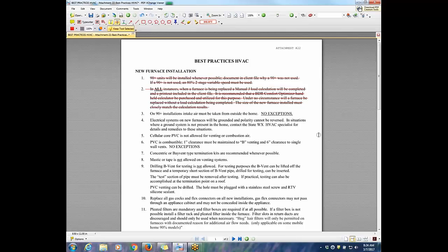And now that appliance, if you do it that way, is no longer a direct vent appliance, so it doesn't fall under the venting rules for a direct vent appliance. It now becomes a mechanically vented or mechanically drafted appliance, and it falls under a different set of rules. Plus, you're defeating the whole safety purpose of that furnace. The reason we run the intake to the outside is to absolutely prevent that thing from backdrafting. If you only run the exhaust to the outside and leave the intake open to the house, yes, you can backdraft that piece of equipment.